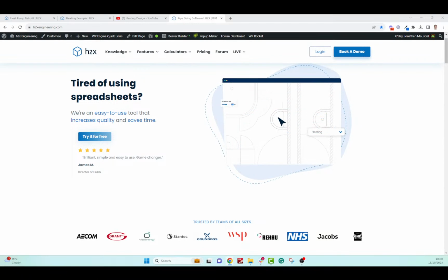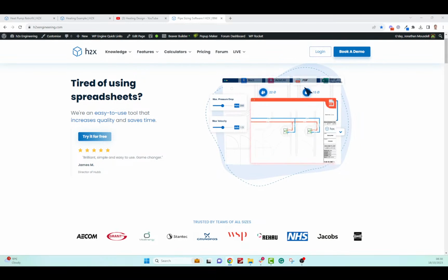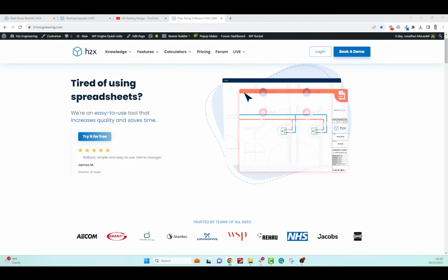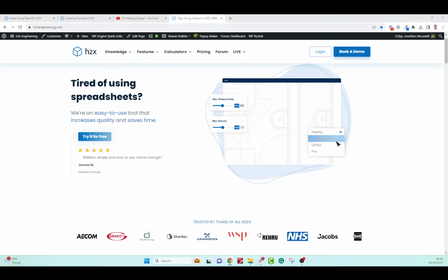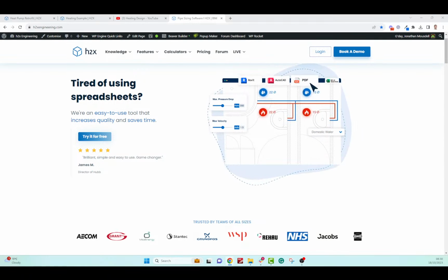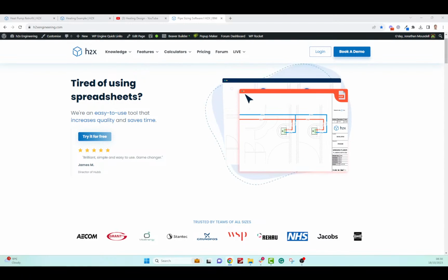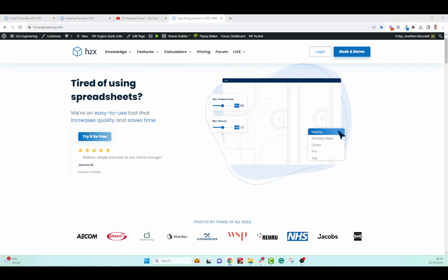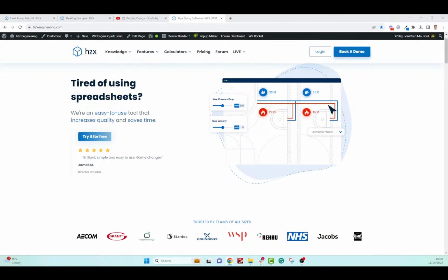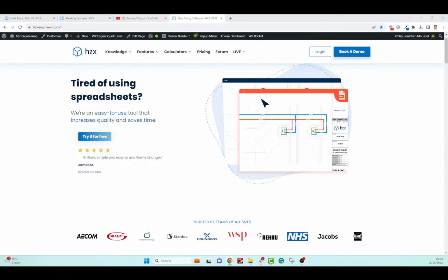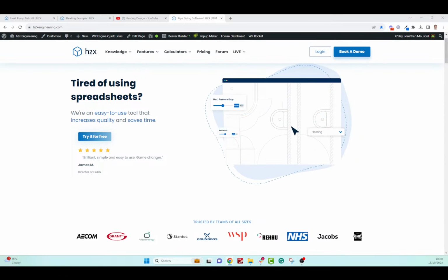So you can put all your Stelrad ones in, and when you start your next project, you just duplicate your template project and you'll have all of the radiators that you've specified. That template project goes for other things as well. If you want to put all your rates in, set your velocities up, all your materials, add your Stelrad radiators, you can do all that in a template project, and every time you start a new project, you've got it all there for you.